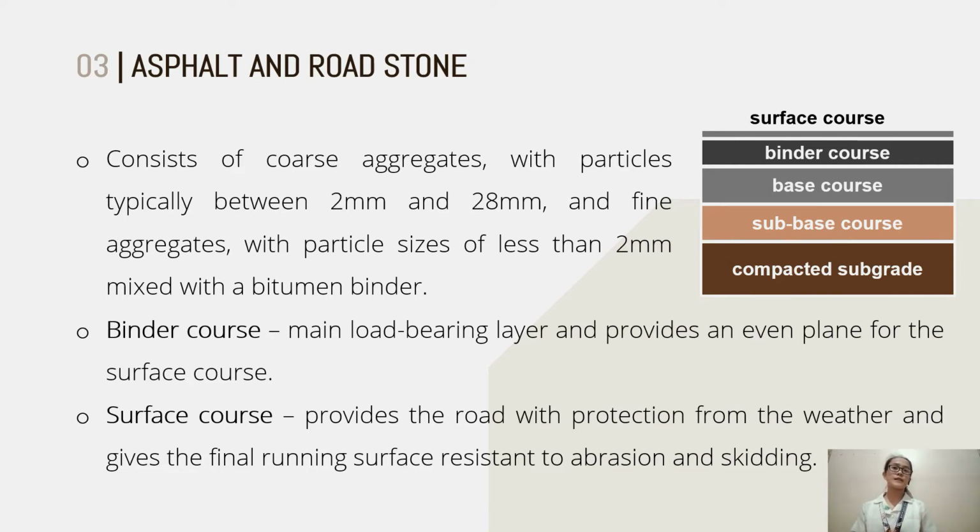Increasingly, mixes are being developed, and these are known as thin surfacing or stone mastic asphalt, which uses cellulose fibers or specialist binders to obtain higher strength with thin layers of asphalt. So the main goal of this development is to provide increased resistance to deformation where traffic density is high, and to reduce surface water spray and vehicle noise.